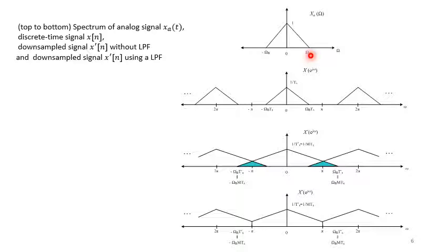Okay, now you understand. I think it was the first topic that we studied about sampling the continuous time signal, right? So when we sample a continuous time signal, if we look in the frequency domain, we see it is basically producing replicas of the Fourier transform, right? So, which are around omega s, right? So we have the first replica here, then we have another replica around omega s, then omega 2s, omega 3s, and similarly minus omega s, minus 2 omega s, and so on, right?